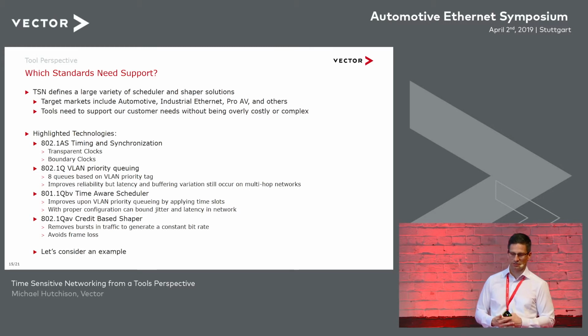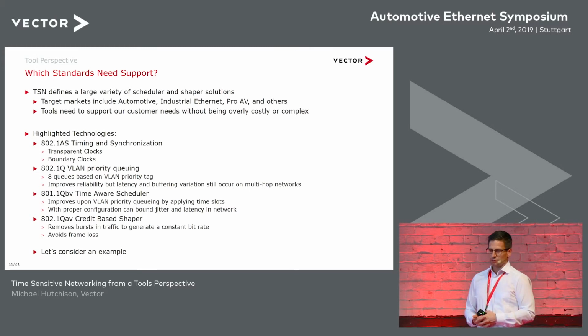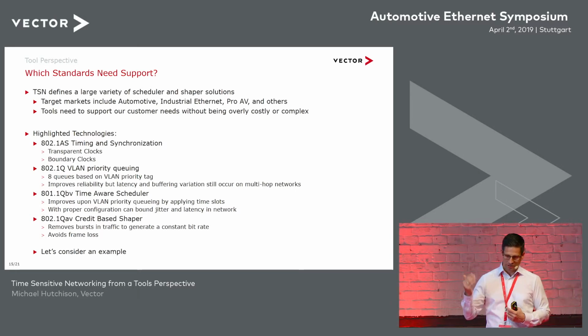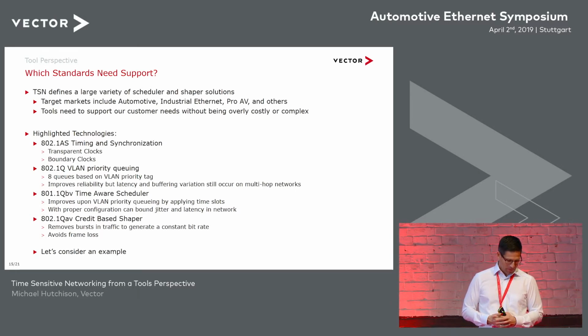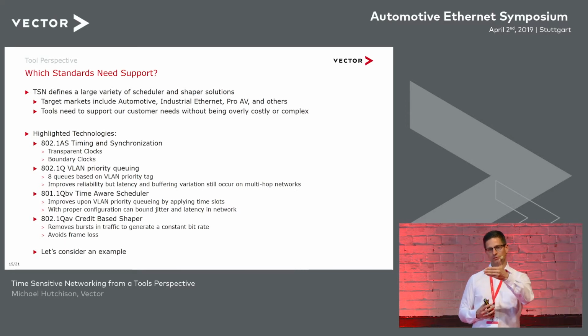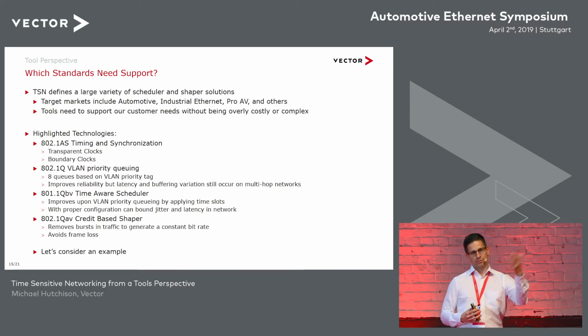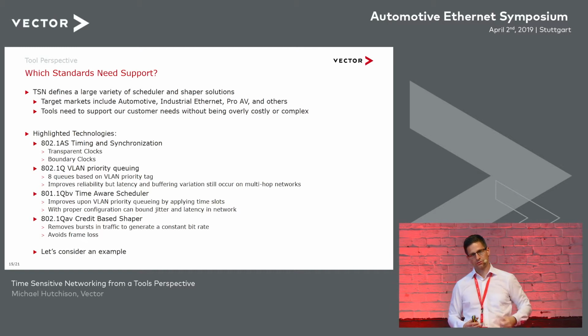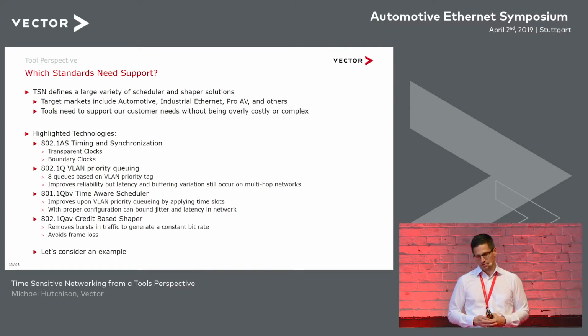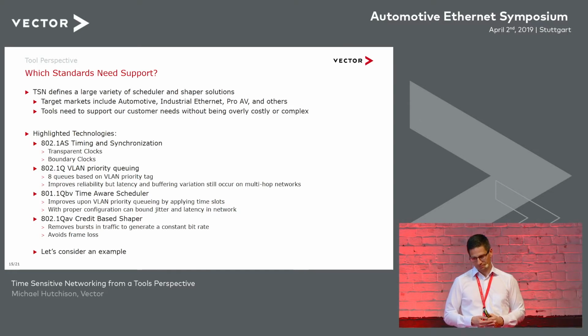That's where we start to get into time-aware shaping. Time-aware scheduling and shaping is advantageous because if I have 6 switches that are cascaded one after another, I can ensure that by the time my packet enters the first switch and leaves, the second switch has the gate open and that packet is going to flow straight through the network. So I eliminate jitter and buffering through the network. So we see this as another technology that can be very advantageous.